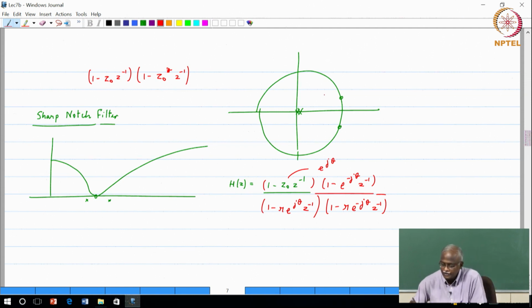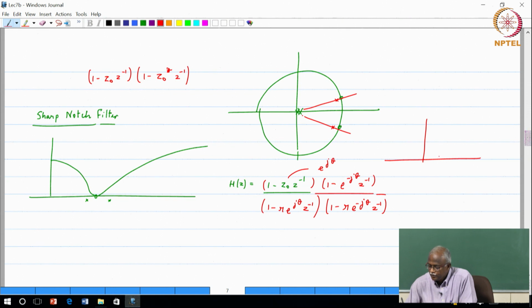Basically what we are saying is we remove these poles; if you look at this, I have put a pole here and a pole here. Will that work? Does that give you a sharp notch filter? The answer is yes, because when you come close to the 0, it will dominate and force the function. Anywhere you go further away, the pole and 0 more or less match each other in terms of the magnitude response. So, the frequency response that you will get is a notch at 0, but pretty much everywhere else a flat response. So, you will have a fairly sharp notch.